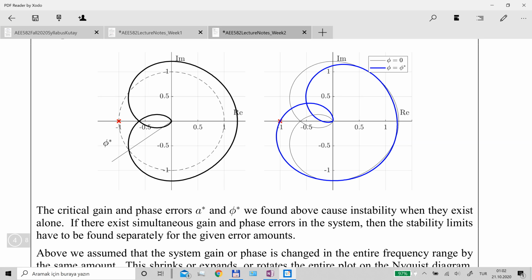In terms of angle, your system may have a very large phase margin. But if that phase margin occurs at a very high frequency, then from a practical point of view, the benefits may not be that much.